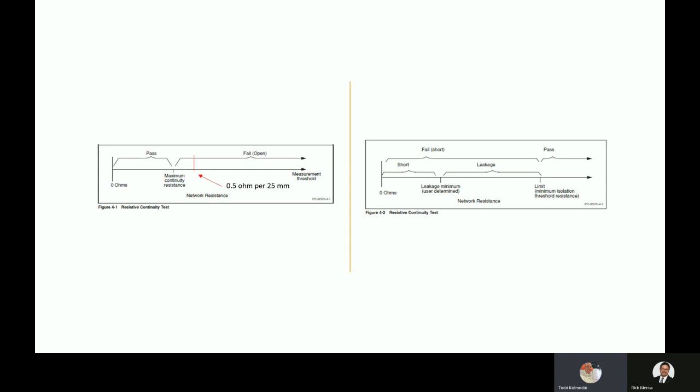So when you get extremely long traces and you're trying to test at test level B, where we want 50 ohms, but most of us use what today is 20 ohms or less, and class 3 product, test level C, 10 ohms or less. If you have a real long trace, you might have that one trace in the board coming in at 17 and a half ohms or 20 ohms. And the rest of the board passes, but you just can't get this one to pass.